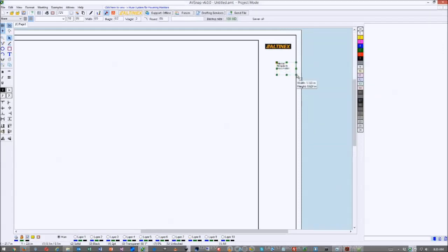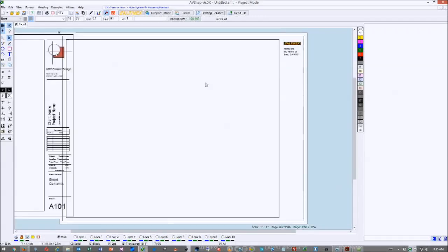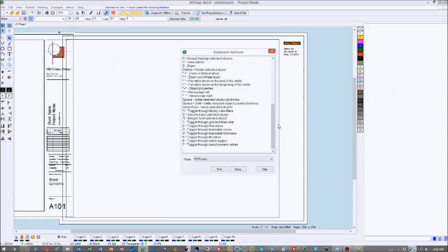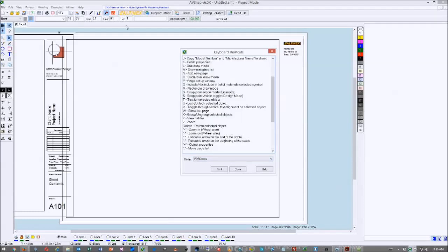And notice that I always use my left hand. If you see what I'm doing, I move really quickly, and a lot of times I use my left hand. As you remember, pressing F1 creates a shortcut list. And I've been telling people over and over again, if you want to work fast and efficiently, just print this out and put it in front of you, and in about a couple of weeks, you will not be using the mouse moving all around the screen.